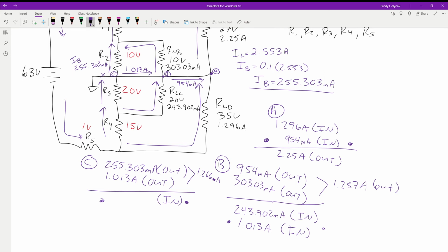So in this case, the bleeder current was on R3. This one would actually be flipped around. Yep, it'd be going in. Because the bleeder current here has to go somewhere. And if this has current that's coming up through here and then turning this direction, this isn't bleeder current because it has current for the load that runs through it. Bleeder current never touches the load. So all we're doing is we have a total amount of current moving through the circuit and we're just rerouting it different directions. That's all we're doing.